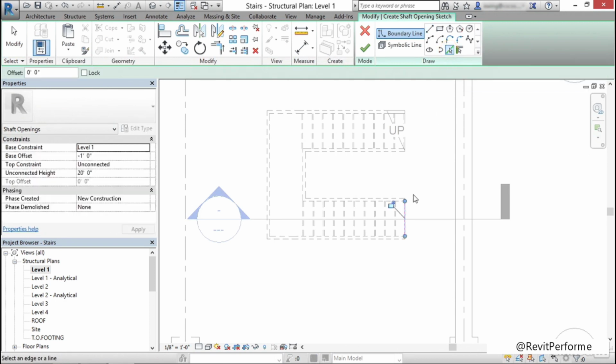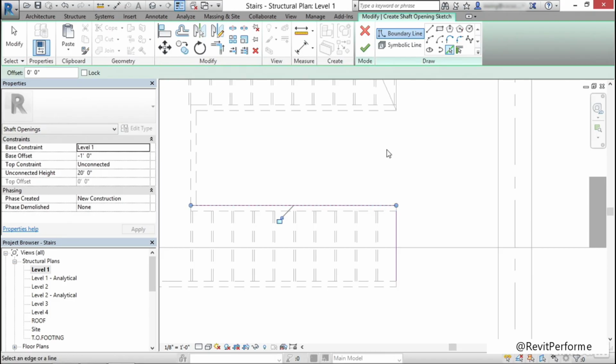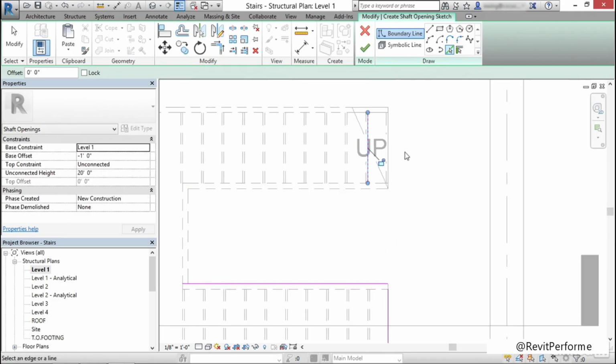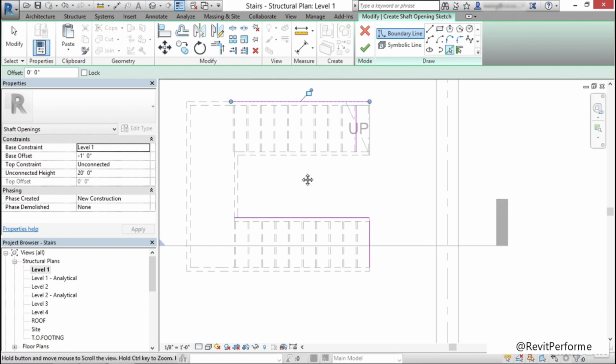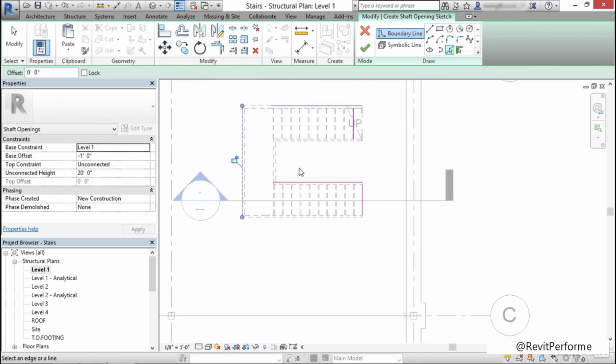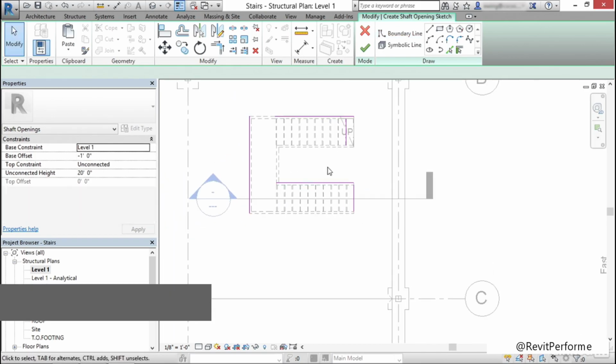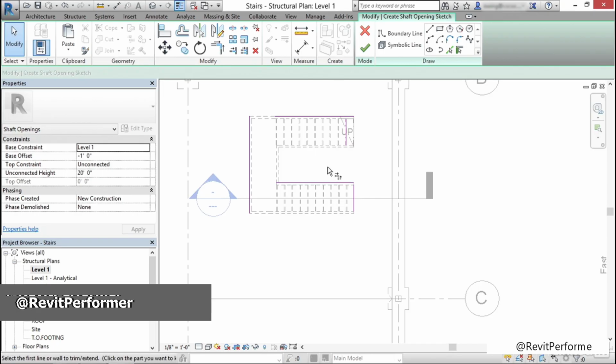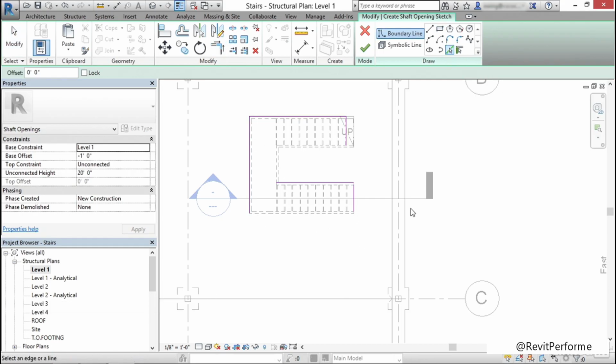I'm going to go here, to here, to here, to here, and then to here. Got a lot of trimming to do. Type TR for trim. Well, here. Trim from here to here. From here. Oh, we need one more line, so I'm going to click on Pick Lines. Upside. Type TR for trim. Trim this up. We're going to trim here to here.